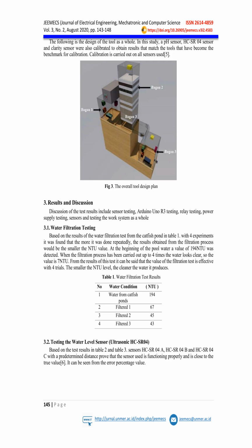3.2. Testing the water level sensor, ultrasonic HCSR04. Based on the test results in Table 2 and Table 3, sensors HCSR04A, HCSR04B, and HCSR04C with a predetermined distance prove that the sensor used is functioning properly and is close to the true value. It can be seen from the error percentage value.